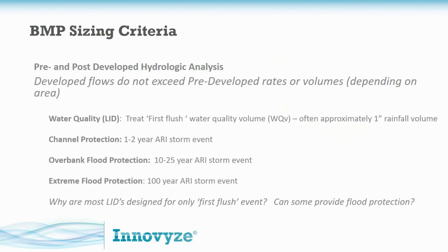If you dumped a lot of water through that really fast, so a high flow event, that velocity will just wash that sand away. So that's why sometimes these facilities can't be used for flood protection. That said, there are a lot of facilities that can, and we'll talk about that. I might call those dual purpose facilities, okay?